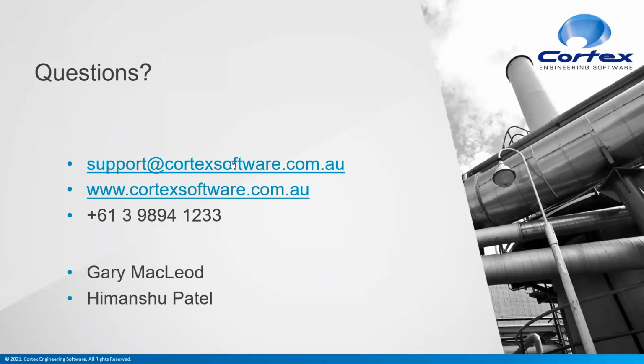What is better, spectral analysis or time history analysis? Okay, well, it really depends. If you really know what the time history looks like, if the shape of your pulse, if you really know and you're certain of that, I would say a time history would be better. If you're a little bit uncertain, then the spectral analysis works really well.